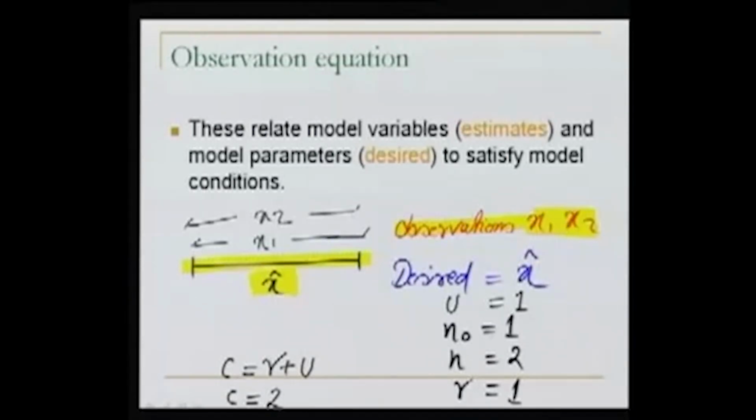Now U here stands for the number of unknowns in terms of the desired quantity. The desired quantity here is the length of the line. So here is one unknown, so U is equal to 1. As in the previous case, N is the minimum number of observations which can determine this unknown, and the actual number of observations taken is larger. R is the redundancy.